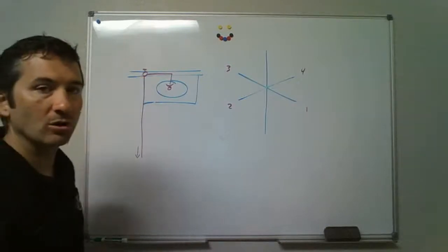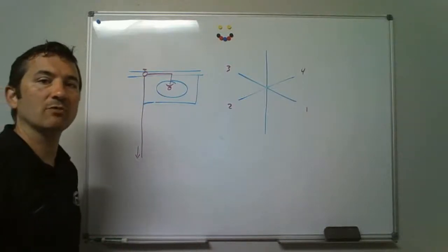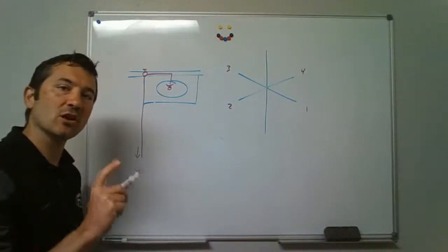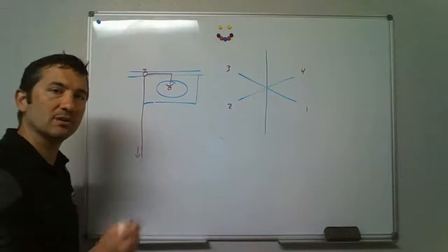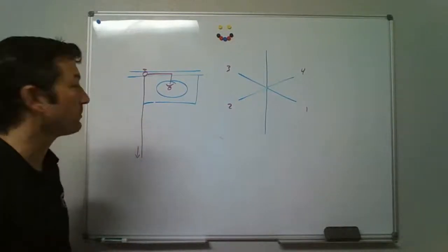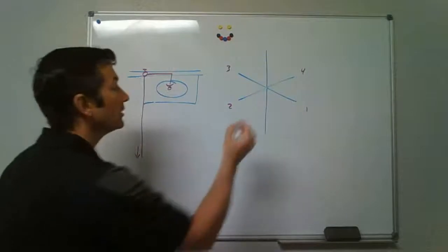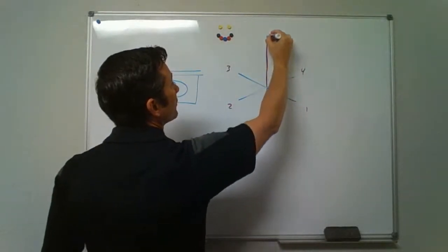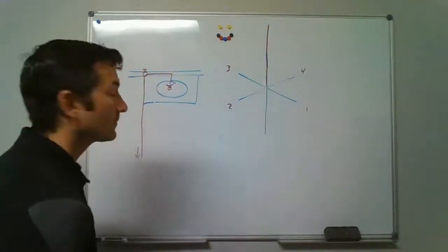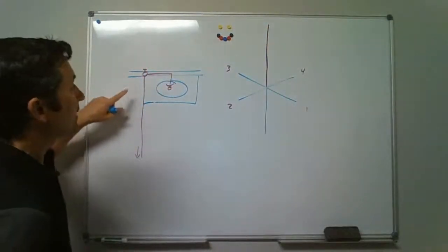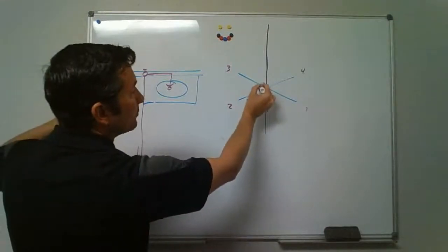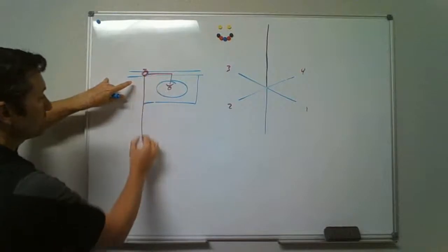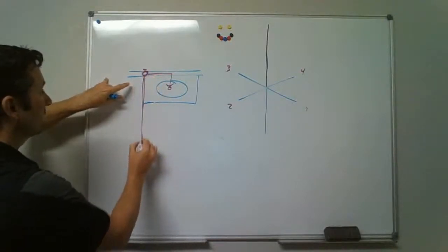The circle on the bird's eye view drawing represents a vertical line. A vertical line in real life is always going to be up and down. Straight up and down is going to be a vertical line on your isometric paper. So when you see the circle, just come over to your isometric paper and draw a vertical line going up. So we drew a vertical line. Now stop it at one of the cross sections, and so we just drew this. We're going to now draw the horizontal drain line, this line right here.